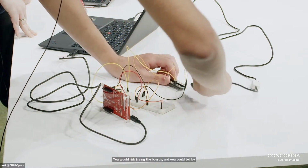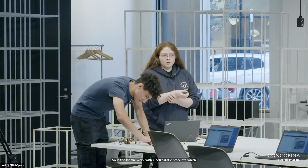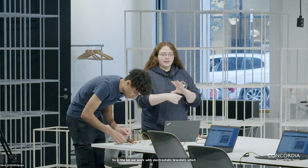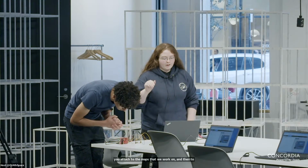In the lab, we work with electrostatic bracelets, which you attach to the mats that we work on and then to your wrist, and that allows any static to discharge safely and not right into the boards.